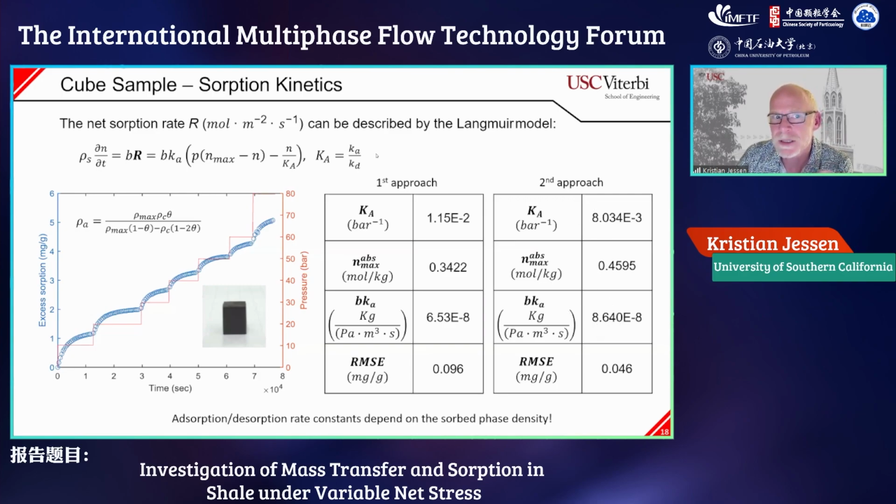And the reason for it is that whenever we convert excess adsorption data to absolute adsorption that we need for the Langmuir model, we make an assumption about the adsorbate phase density. For instance, I assume that the adsorbate phase density is constant. That would mean all the way along this process, the adsorbate phase would be the same, regardless of how much I have adsorbed onto the surfaces. And that may not necessarily be true. So the model that is written here attempts to change the adsorbate phase density as a function of the fractional coverage.